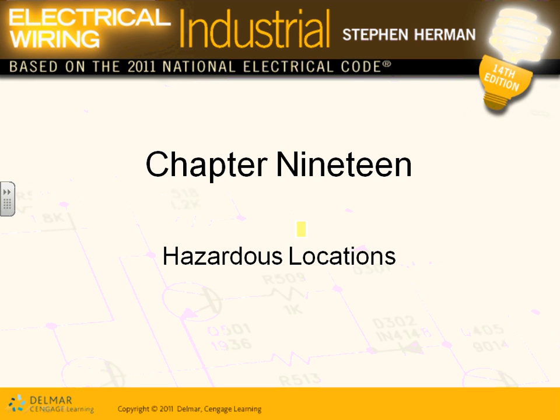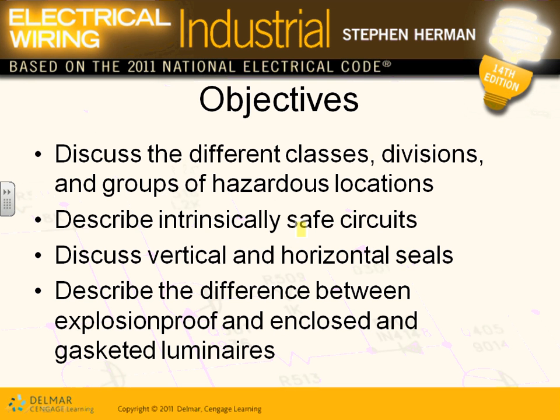We as engineers don't get into classifying gas as electrical engineers. For the most part, we walk into a building and we ask the building officials and so forth to classify what classification this area is. Based on the classification of this area, we decide what wiring methods we need in this area. So that's the thing that you need to know.